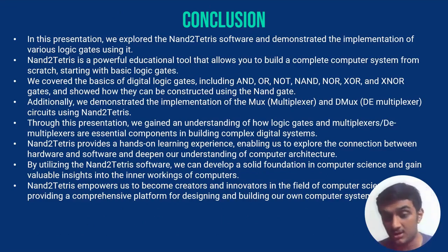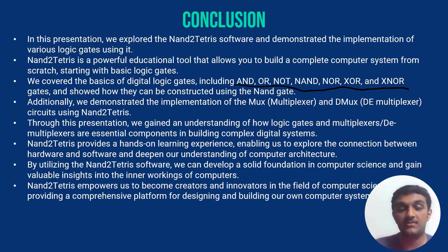In conclusion of this presentation, we have explored NAND2TETRIS software and demonstrated the implementation of various logic gates used in it. And we have also explored how to use the hardware simulator in NAND2TETRIS, and I have also demonstrated how we can implement the AND, OR, NOT, NAND, XOR and XNOR gates, showing how they can be constructed using the NAND gate as well. We have also demonstrated the implementation of MUX, Demultiplexer and other circuits using NAND2TETRIS.